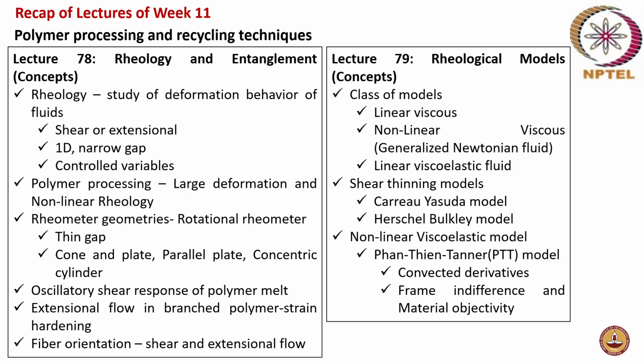So in your Herschel-Bulkley model, this applies for shear thinning systems where you start seeing shear thinning after the material crosses a yield stress. After crossing the yield stress only you will actually see the flow in such kind of materials.